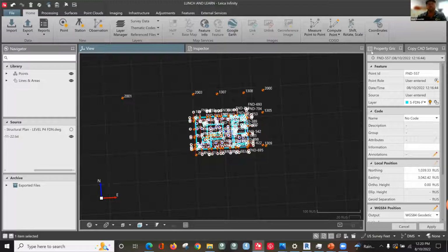One of the things you will do with that IFC is bring it in. You will select the job that you just transferred from your top carousel in Captivate, and you will hit view and edit data and add your IFC at that point. The reason we like to do it that way is an IFC can really bog down certain controllers, but if you attach it instead of import it, you can select just the points that you want, not all of them, and it won't bog you down and make your program run really slow. And with that, we're at 21 minutes.